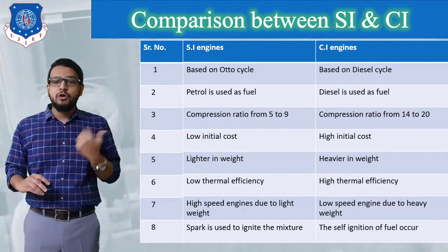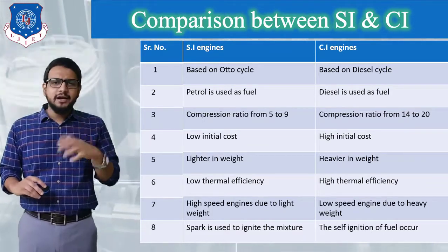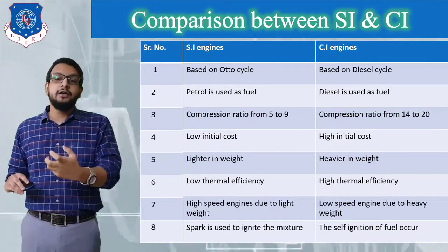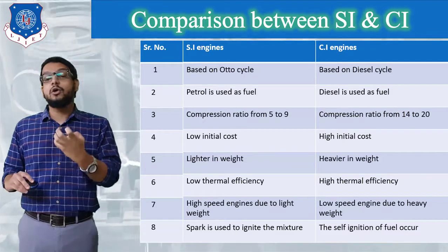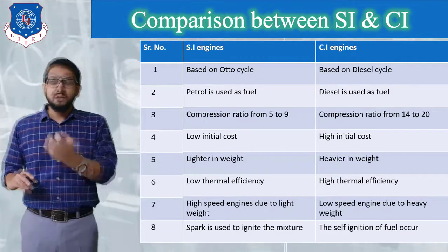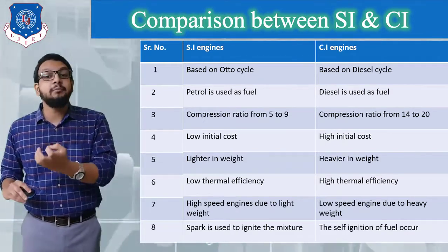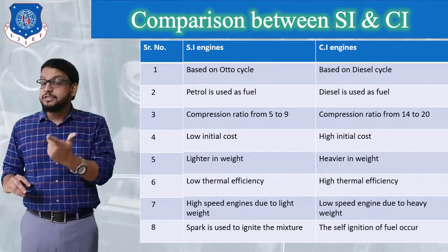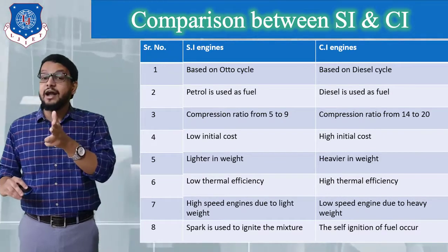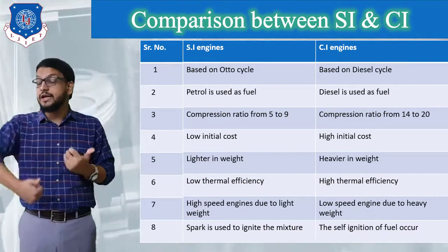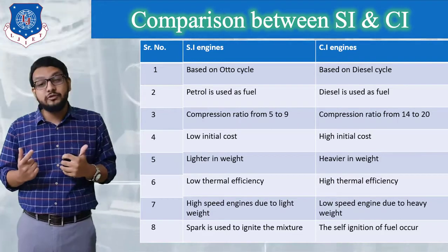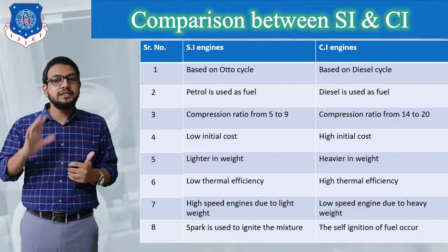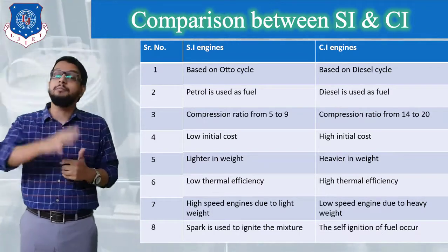Now taking the case of cost. In which case will the initial investment be higher? In the case of the diesel engine, the initial investment will be higher, as we know that diesel cars are costlier. Why? The reason is that the diesel engine has to withstand high temperature, as we are only compressing air, and because of that the temperature of the cylinder and piston will be much higher at the end of compression. So the thickness of the cylinder and piston is going to increase, and because of that the overall cost of the engine is going to increase. So diesel cars are much costlier compared to petrol cars.